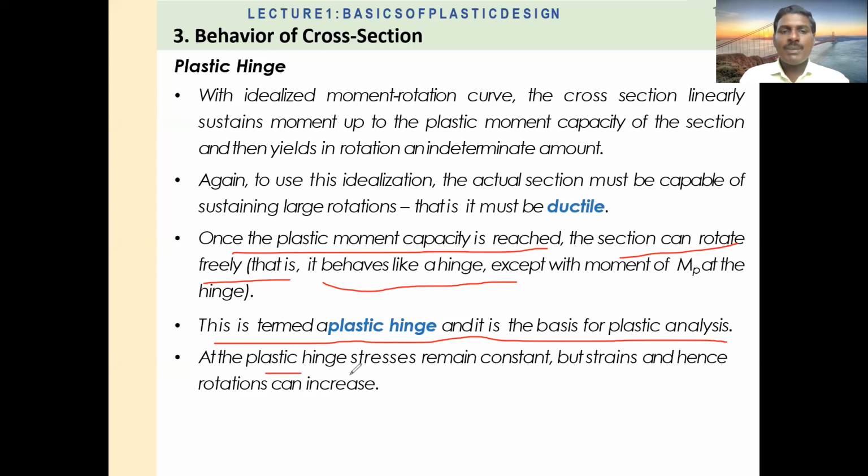And at the plastic hinge, stress remains constant, but strain, hence rotation, can increase. It means again strain increases, but stress is constant. So that is the plastic hinge. So where the plastic hinge forms, that we have seen here.